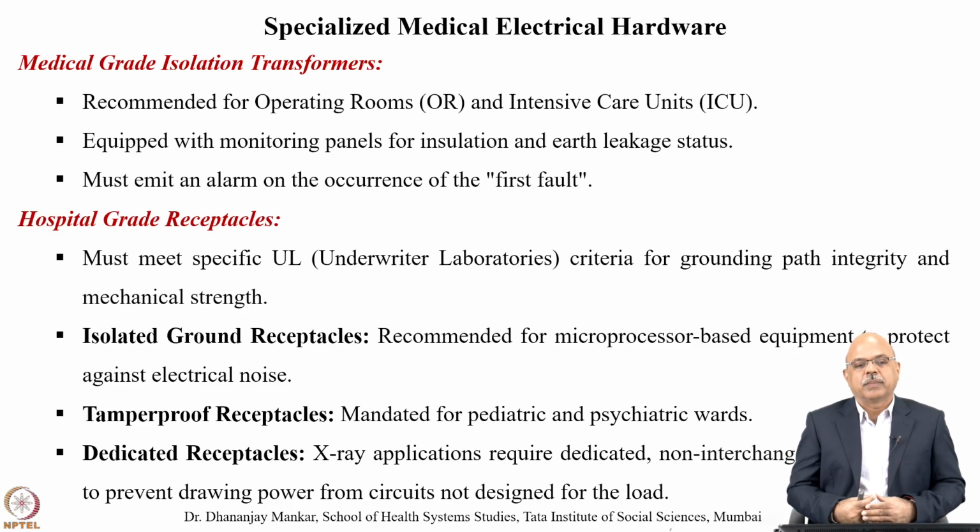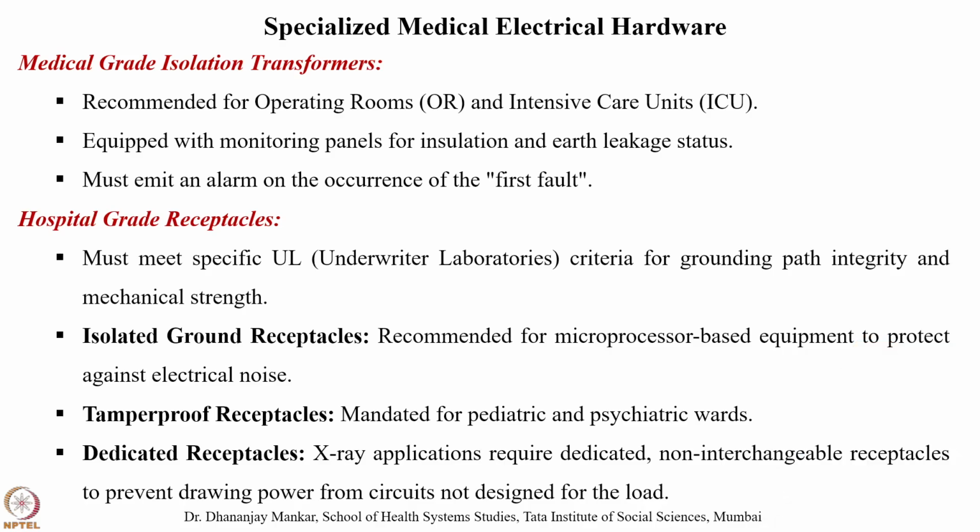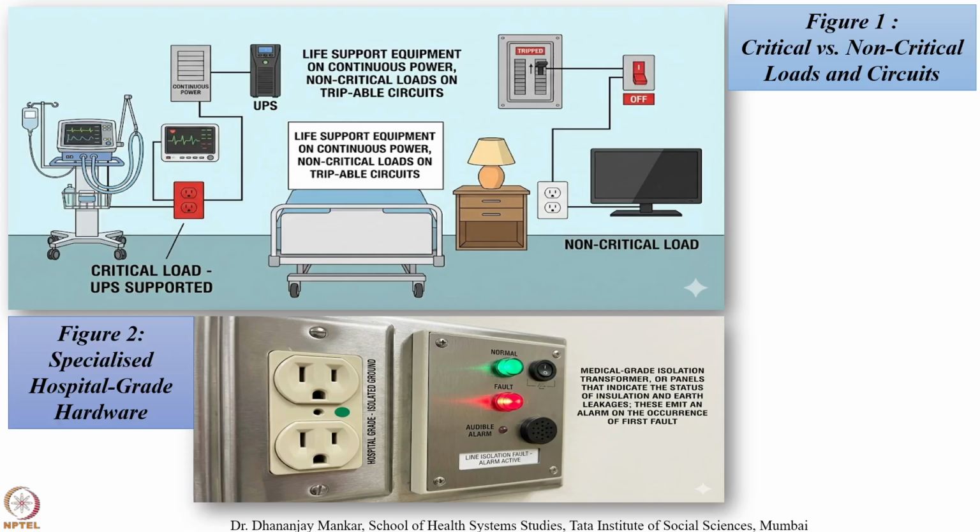Hospital grade receptacles must meet specific UL, that is Underwriters Laboratories, criteria for grounding path integrity and medical strength. Isolated ground receptacles are recommended for microprocessor-based equipment to protect against electrical noise. Tamper-proof receptacles are mandated for pediatric and psychiatric wards, and X-ray applications require dedicated non-interchangeable receptacles to prevent drawing power from a circuit not designed for the load.